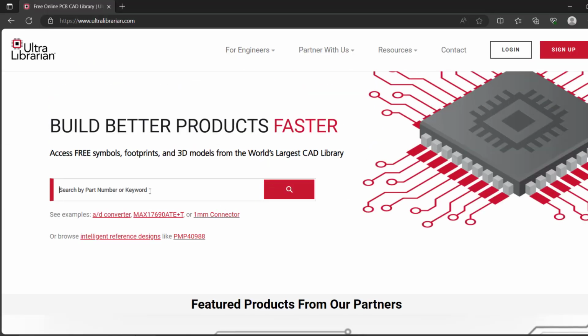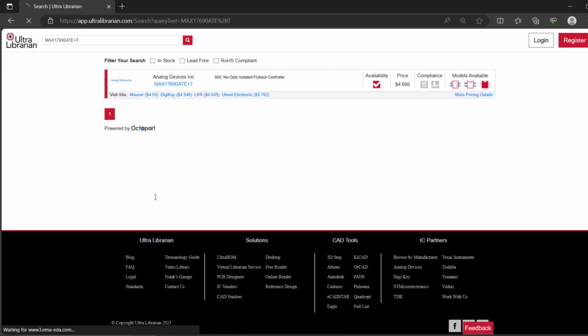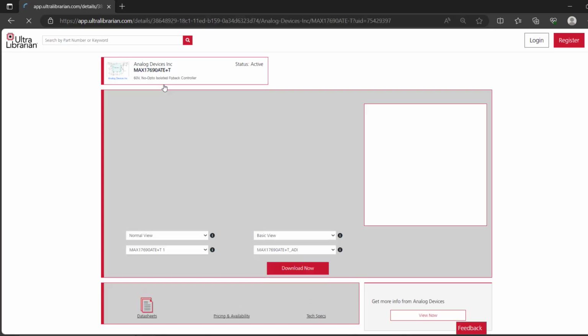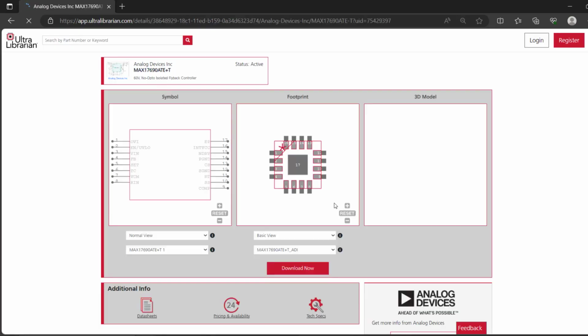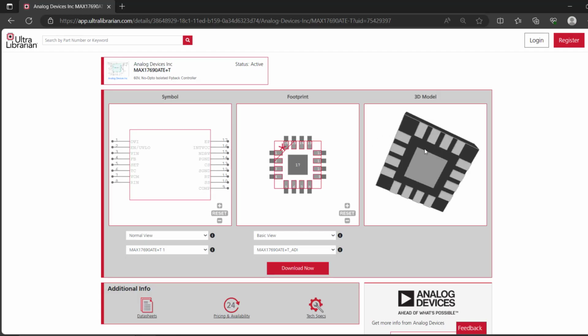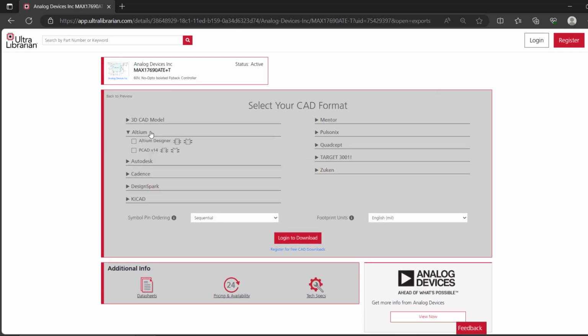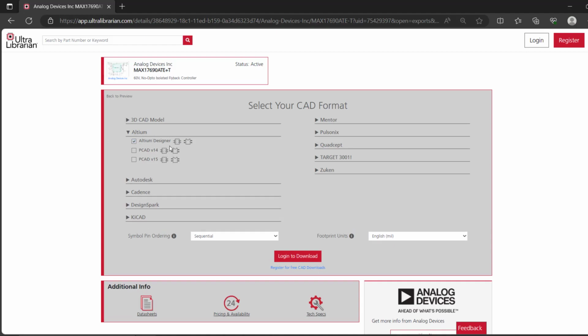Then, use their search feature to find the required components by name, manufacturer, or part number. Download the schematic symbols and PCB footprints in formats compatible with Altium Designer. Import these files into your Altium Designer libraries, ensuring they are correctly categorized. After importing, review and customize the components to match your project's unique requirements. This process significantly expedites component selection and integration while ensuring compatibility with Altium Designer.